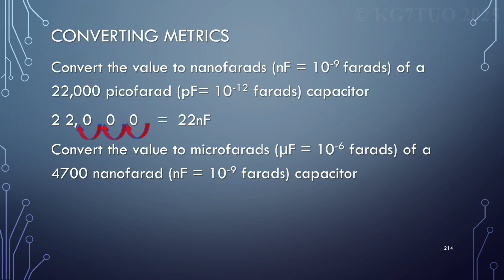I heard a 4.7. And then when you're doing the math, do you do the largest first? It's whichever way you're going. If we had 4,700 microfarads converting it to nanofarads, we'd go the other direction. So if you're going from a smaller number, minus 9, to minus 6, you're moving to the left. Okay, boom, boom, boom. Three decimals. That's why this is much easier.